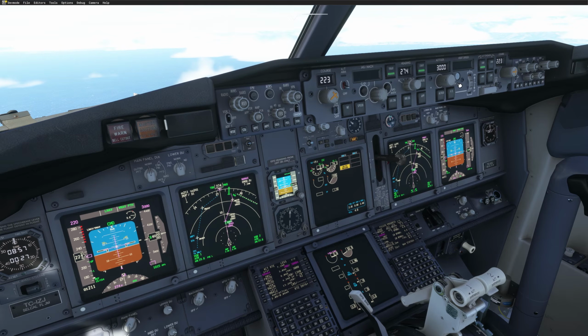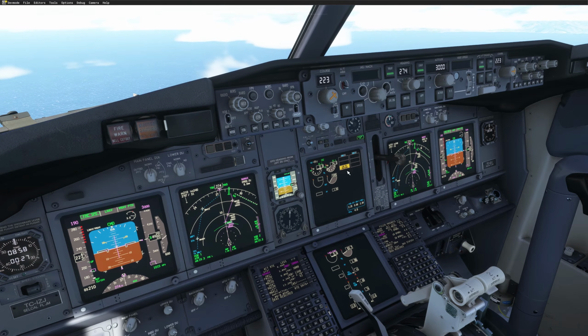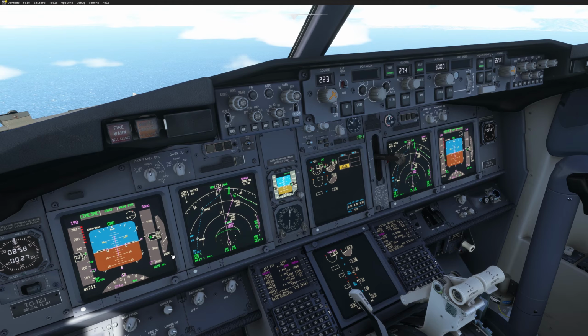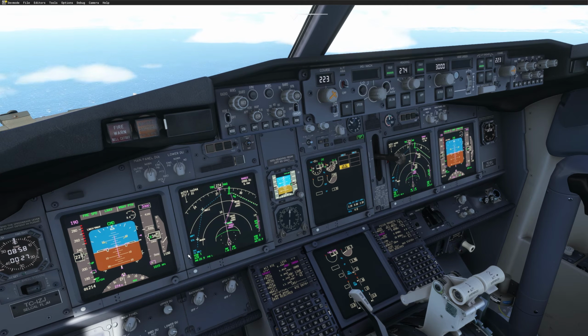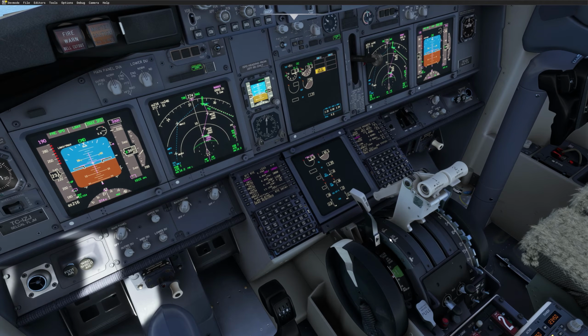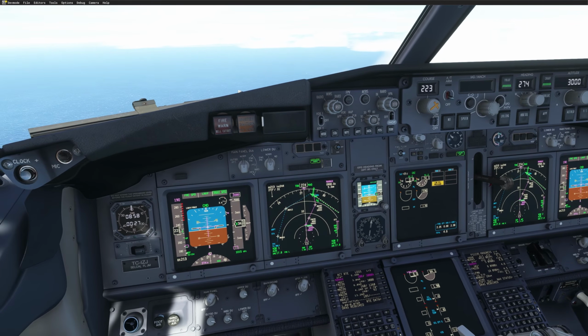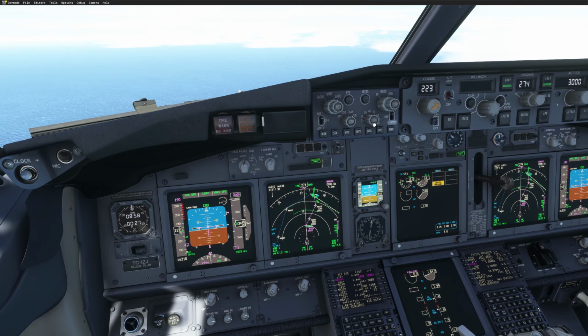And I will start the descent now. So I press descend now. And now the commanded descent is 1,000 feet per minute. Because we are below profile, so she will command 1,000 feet per minute. We can go flaps 5. Use a bit of speed brake, as I don't want to touch my thrust, to show you how easy you can fly that airplane if you don't touch the thrust in single engine condition. Now she's perfectly trimmed, and I didn't touch anything since we did it. So that's the secret.